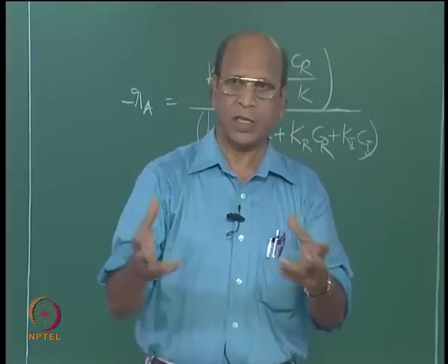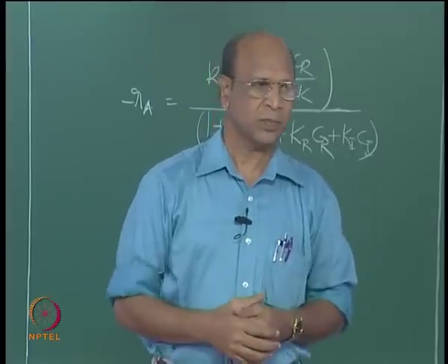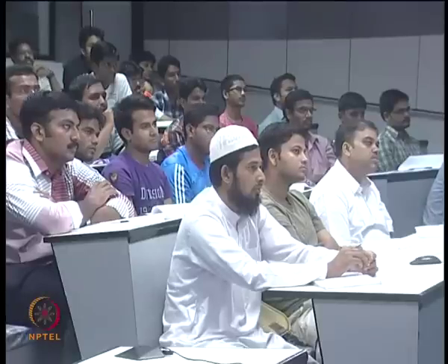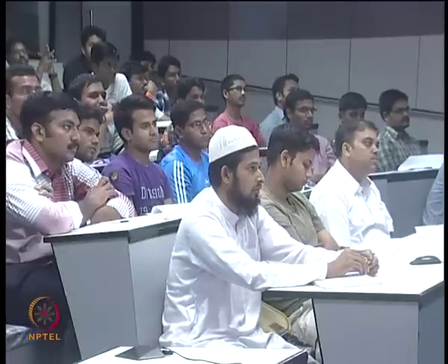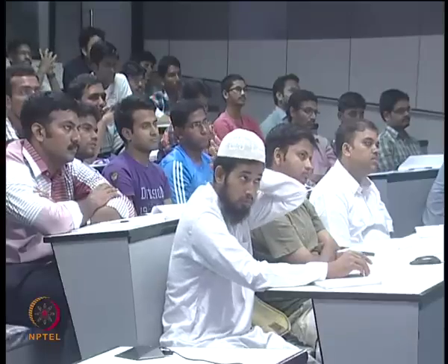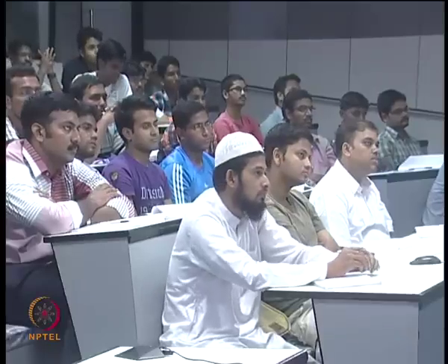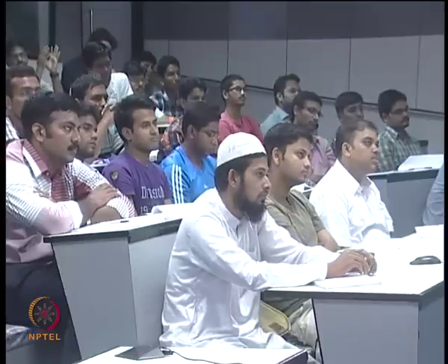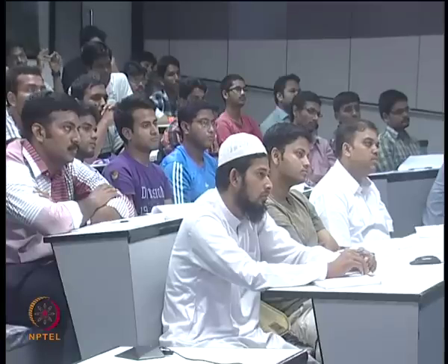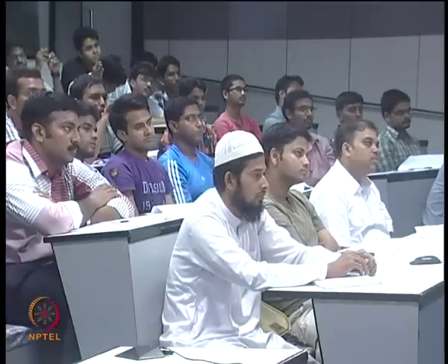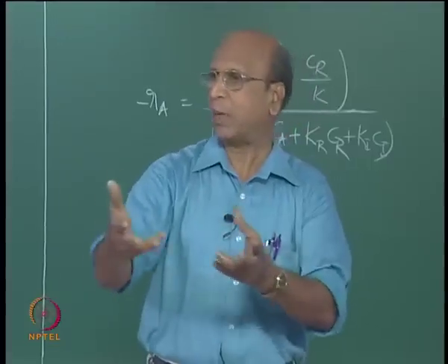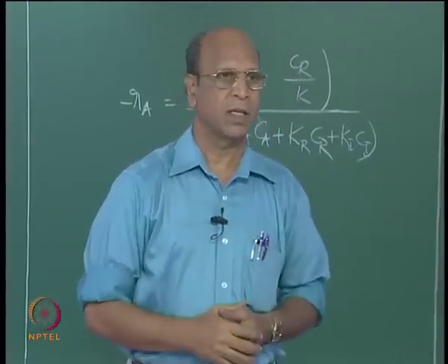Yeah, but what does that finally give you for this procedure? Number of stages. This will not give you a number of trays. Thermodynamics will give you only the equilibrium diagram. So, from thermodynamics simply take the equilibrium diagram. Okay, if you are assuming even enthalpy, it is the simplest case. And then from energy balance, from material balance you will get the operating lines, correct?